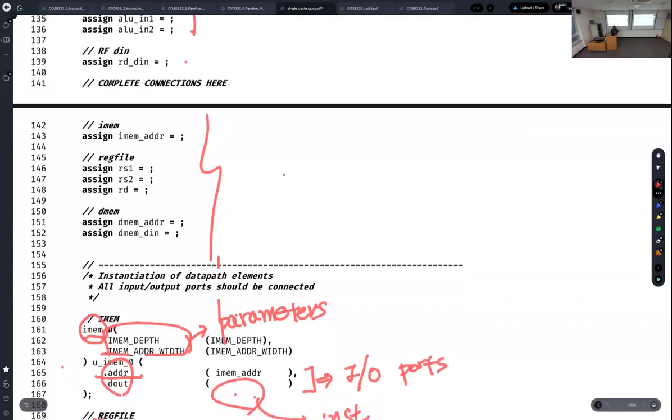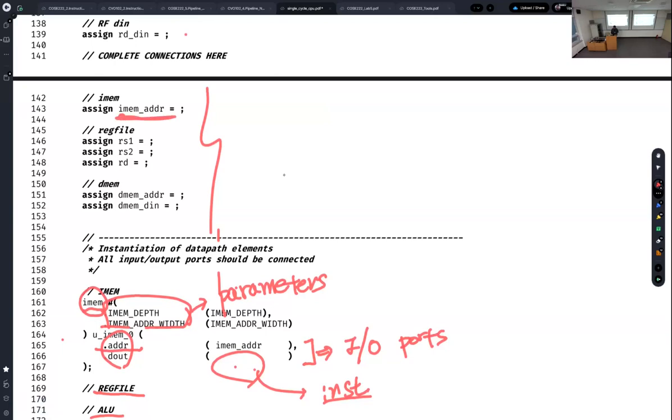Actually, you can just define the appropriate bit signals. For example, the IMEM address. PC is connected to the IMEM address port. But if you see the instruction memory, when the address is incremented by 1, the actual address 1 is assigned 4 bytes, right?